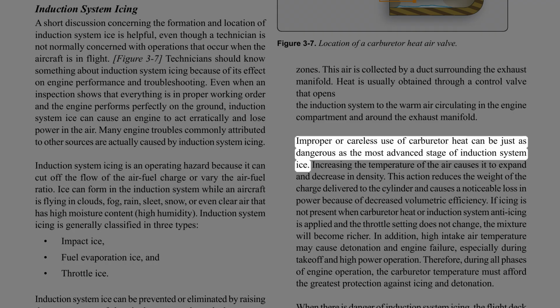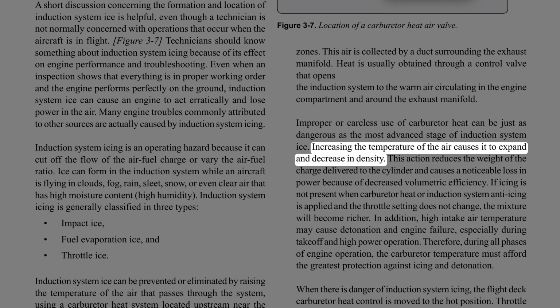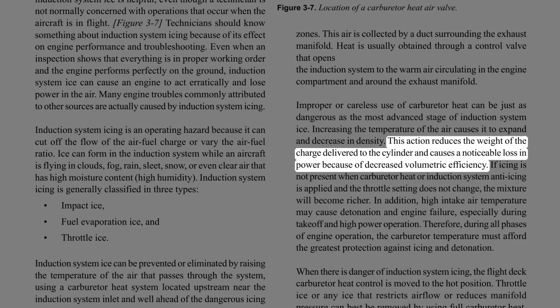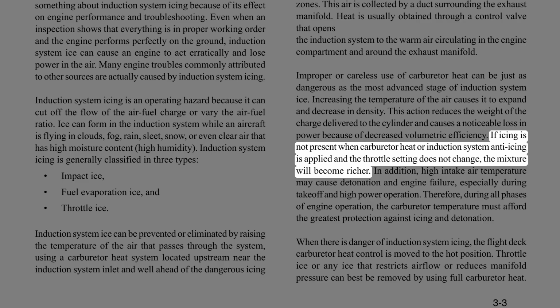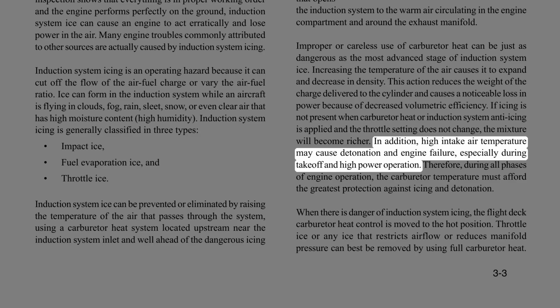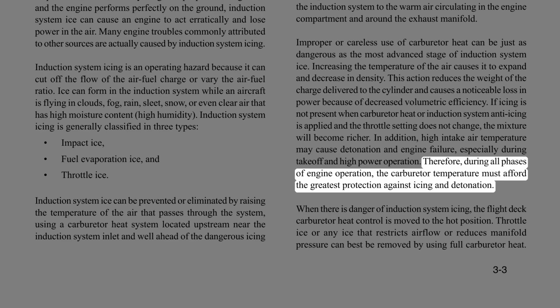Improper or careless use of carburetor heat can be just as dangerous as the most advanced stage of induction system ice. Increasing the temperature of the air causes it to expand and decrease in density. This action reduces the weight of the charge delivered to the cylinder and causes a noticeable loss in power because of decreased volumetric efficiency. If icing is not present when carburetor heat or induction system anti-icing is applied and the throttle setting does not change, the mixture will become richer. In addition, high intake air temperature may cause detonation and engine failure, especially during takeoff and high power operation. Therefore, during all phases of engine operation, the carburetor temperature must afford the greatest protection against icing and detonation.